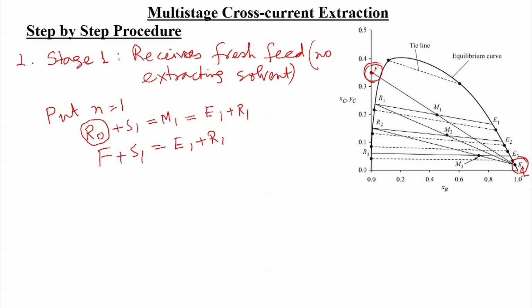I told this earlier also, that pure extracting solvent is not used for the extraction process. This solvent is already received from another extraction process. So, some amount of the solute may be present. If it is 1-2%, then it is coming at 1-2, due to this 1-2% it is not coming at zero. Okay. So, we will be getting the point, this S 1 will be placed here.